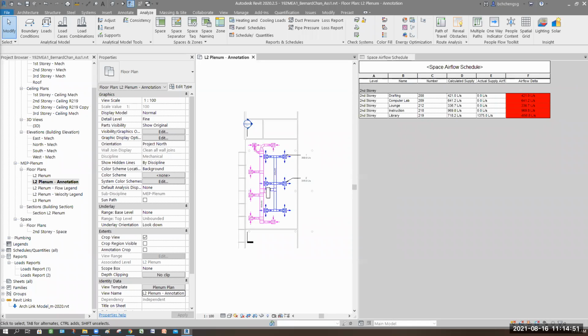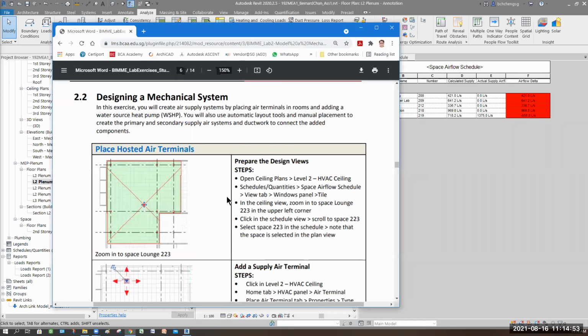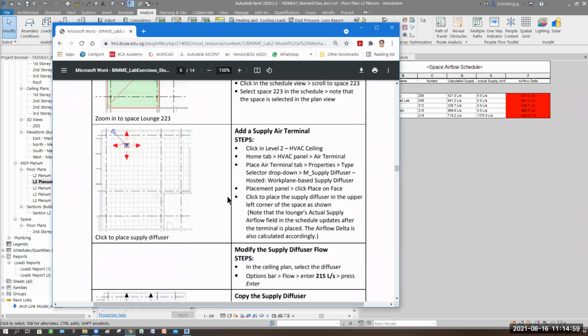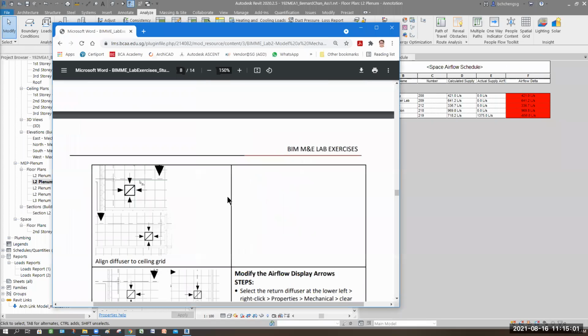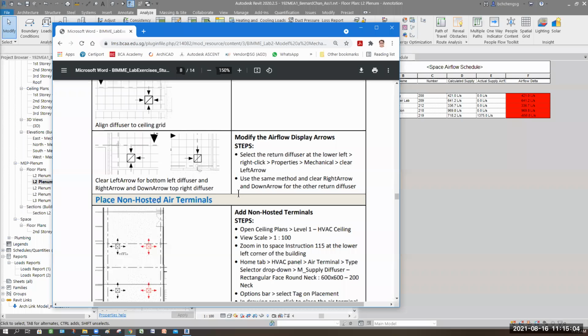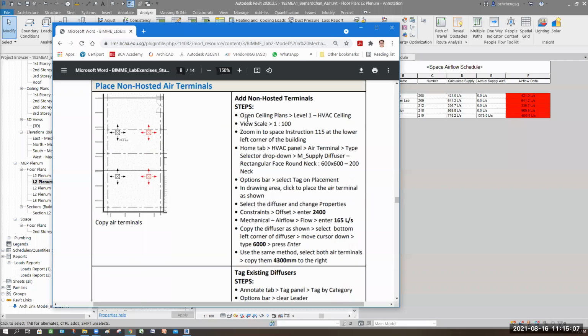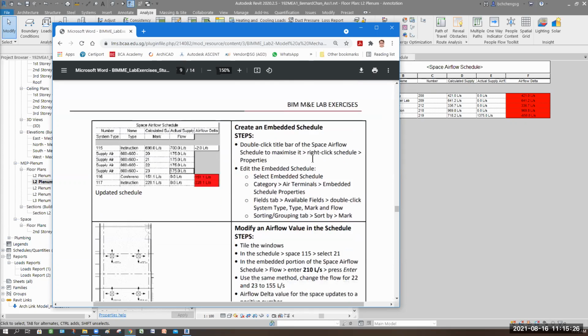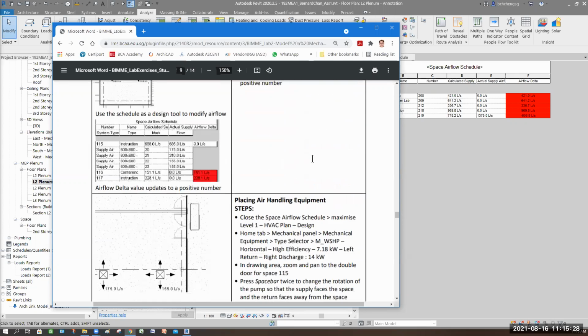So in your notes here, this part is already done. The interesting one is the one that we're going to do. This for non-host, I don't care. This means on other levels. It's this one here. You guys need to learn or memorize this: how to create an embedded schedule based on their cooling system. Maybe they're using ACMV or water cooled like what we are using now. So you can have different types of systems and customize accordingly. This one is at your page 17.